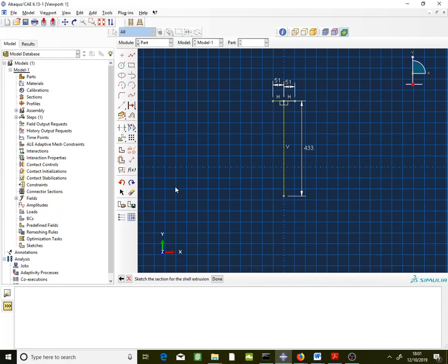You can mirror, or you can redraw the lines from here to here and cancel the procedure, and then another line from here to here and cancel the procedure. Then go into add dimension, click there, go down, and it's 51 as well. Similarly you do it here, and you write 51.